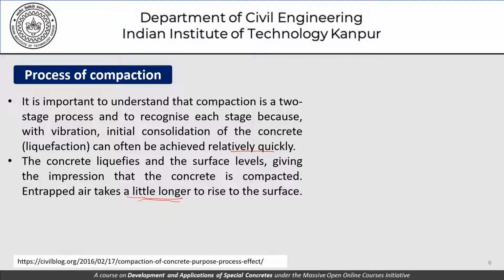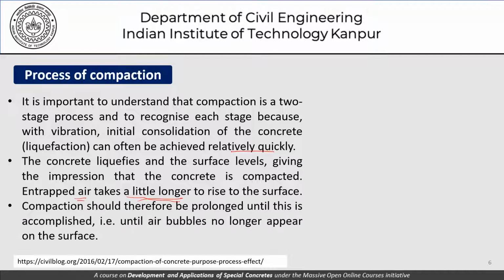This entrapped air is within the concrete. Compaction should therefore be prolonged until this is accomplished. This means release of all the entrapped air from within the concrete. This is accomplished, that is, until the air bubbles no longer appear on the surface.